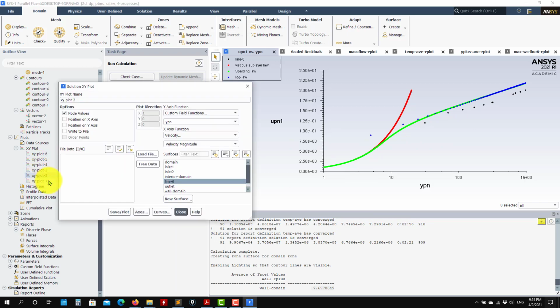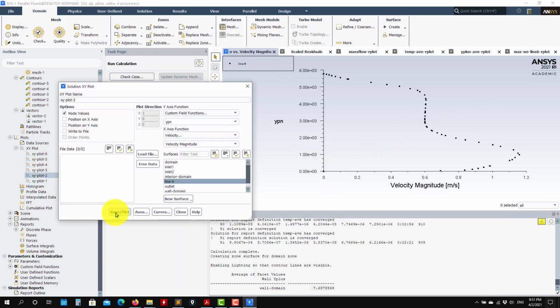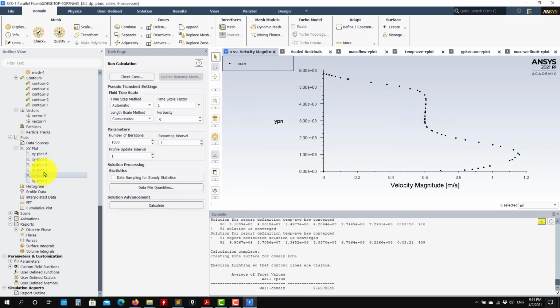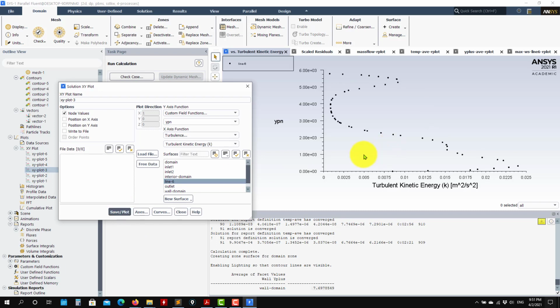As you keep going with the plots here, now we have this one. Again, all these plots will be y plus, normal to the wall, and then you have velocity. So this is dimensional velocity. See that you have the secondary stream, and then the other one passing, and so on. You keep putting your plots. Here you have the turbulent kinetic energy. See that you have a peak here, and then another peak here corresponding to the secondary stream, the other one.